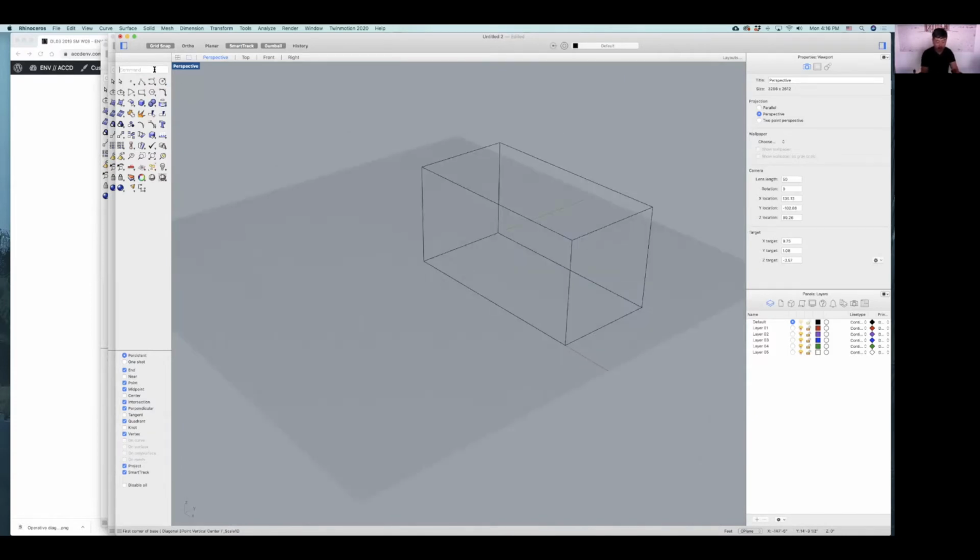So if it's 20 feet, you can type 20 and a single quotation mark. If it's 20 inches, you can type the double quotation mark. So you can enter feet and inches doing this. If you are drawing something like 40 feet and 6 inches, you would type like this to get that number. Okay, so that's how to input numbers.